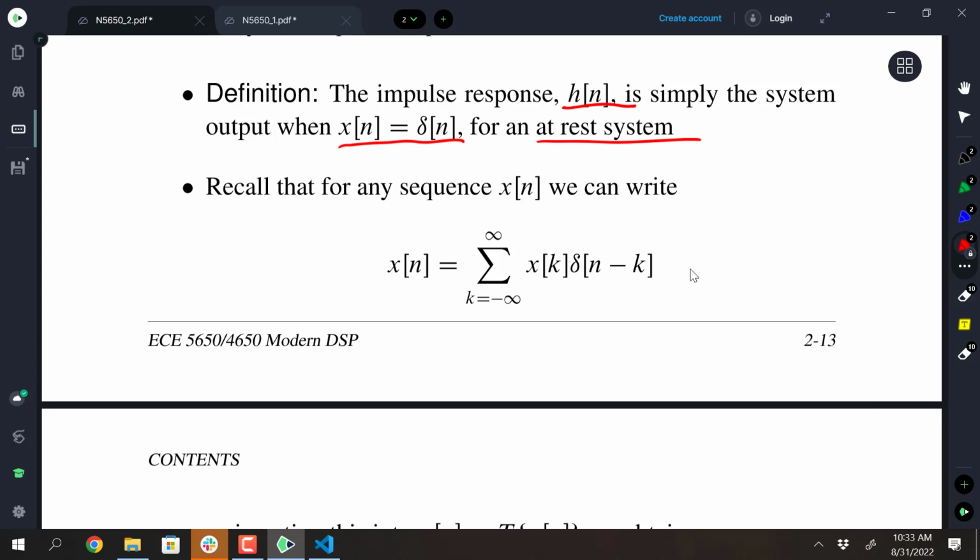For me, it'd be like taking my bottle here and having some sort of a sensor around my bottle measuring the vibration and just pinging it with my finger, just giving it a single ping, which is like a delta. What sort of ringing action happens on the circumference of that cylinder? There'd be some vibrations that get set off. So that's the impulse response.